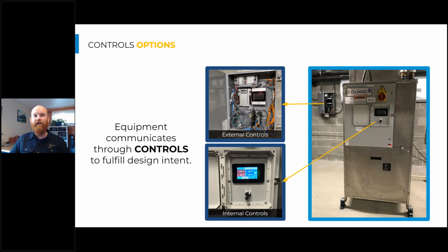And so it's really critical to engage with the manufacturer when setting up an external control system to ensure that the operating parameters and boundaries that you're establishing in that controller will be allowed and permissible for the heat pump water heater to operate at those boundaries.